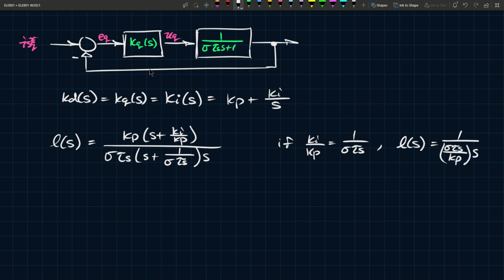So you're left with an integrator with some gain, and that gain is controlled by KP, tau S, and sigma. Tau S and sigma aren't really under our control, but KP is, so we control the time constant with our proportional constant. Then you can write the overall closed loop transfer function as you wish, and you end up with the generic 1 over tau I s plus 1.